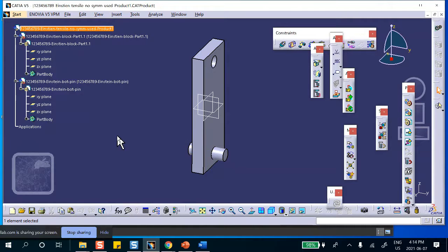However, a word of advice, if the problem is simple enough, go make it. The reason is that when you make an existing component and you do something to the original part, exactly the same thing is going to happen to the thing that you inserted. Okay, so don't do it. I mean, it's up to you.